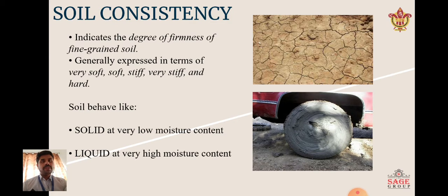Today we will discuss the topic soil consistency of Geotech Engineering. So let's start. Basically, soil consistency is a term which indicates the degree of firmness of fine-grained soil, generally expressed in terms of very soft, soft, stiff, very stiff, and hard.